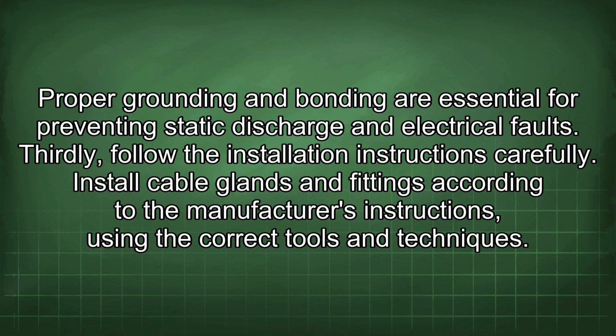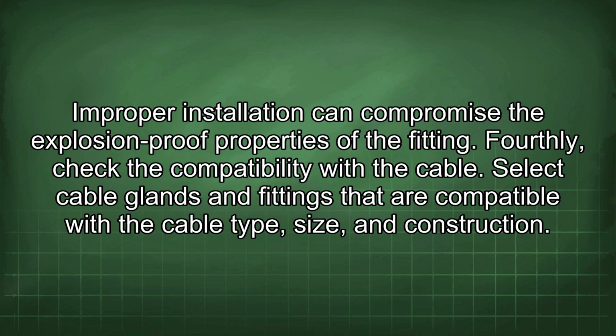Thirdly, follow the installation instructions carefully. Install cable glands and fittings according to the manufacturer's instructions, using the correct tools and techniques. Improper installation can compromise the explosion-proof properties of the fitting.